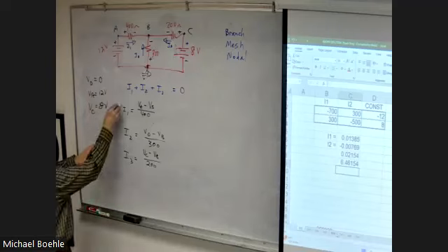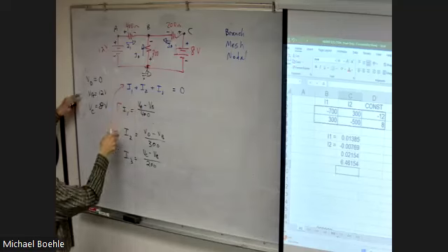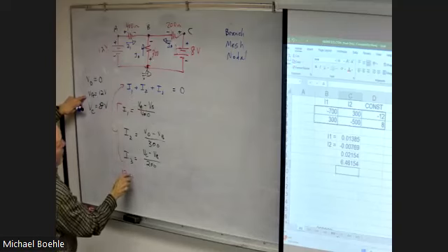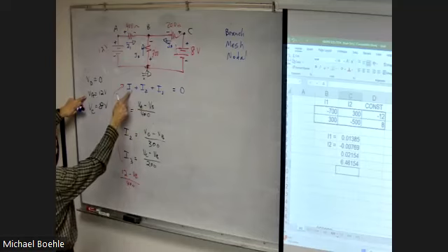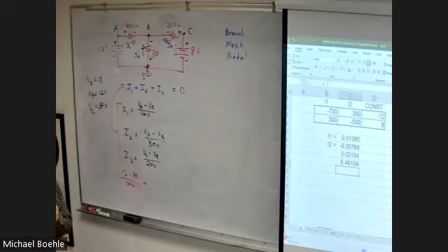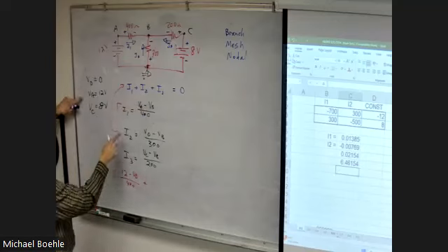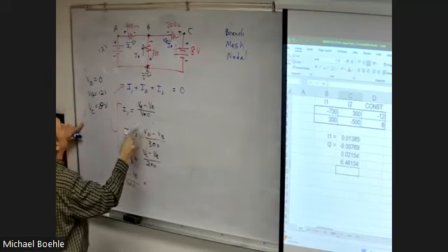And what I'm going to do is I'm going to take these three things here, put them in there. That's going to be my final equation. All right. So current one is voltage at point A, which is 12, minus the voltage at point B, which I don't know, divided by 400. That's current one. Plus, this is one reason I like to do this, right? No negatives this way, right? And you know, negatives just really mess you up. All right. What's current two? Well, current two is voltage at point D, which is 0, minus the voltage at point B.